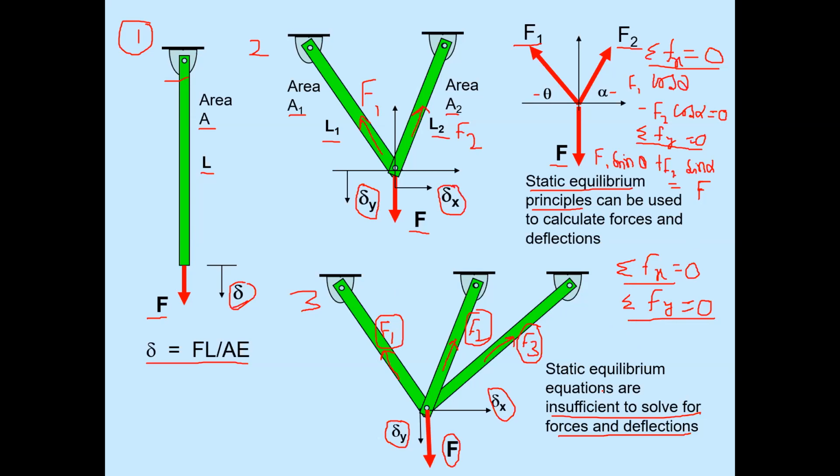So this is known as a statically indeterminate structure. The third structure is known as a statically indeterminate structure. So we can't solve this by just static equilibrium principles. We need some idea of the deflections of the structure in order to analyze this structure. Now, in a later part, I will explain how to solve these kinds of equations by using Castigliano's theorems or the energy methods. Let's move on to the next part.